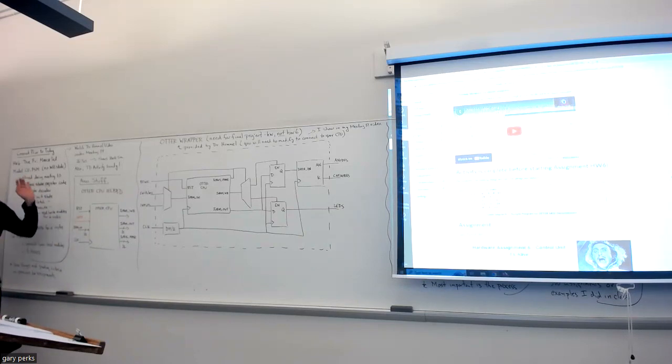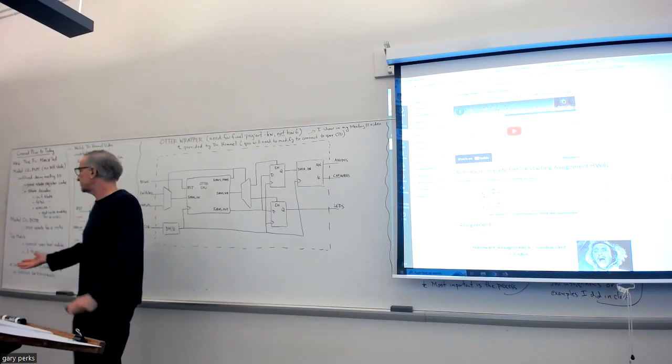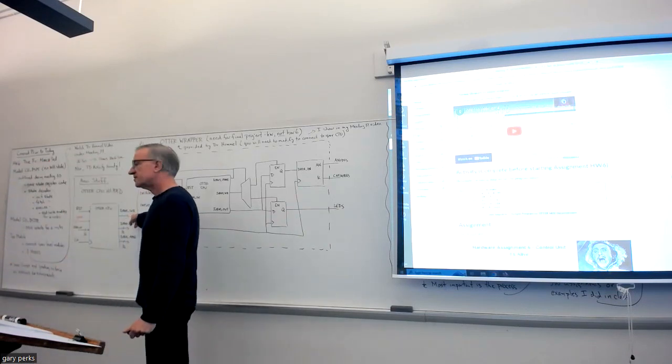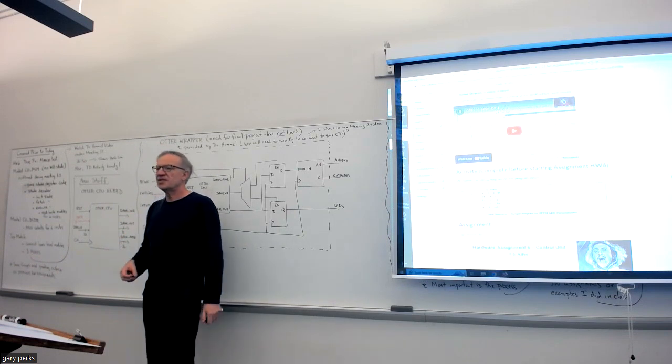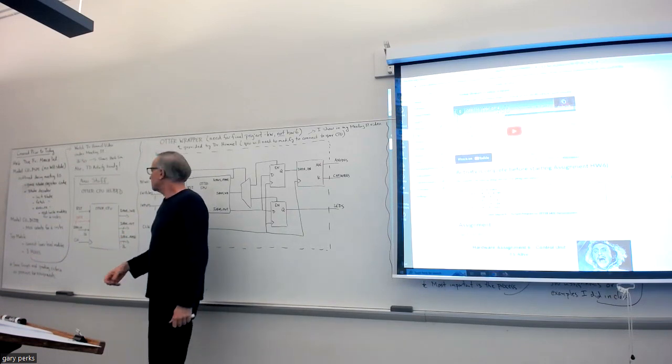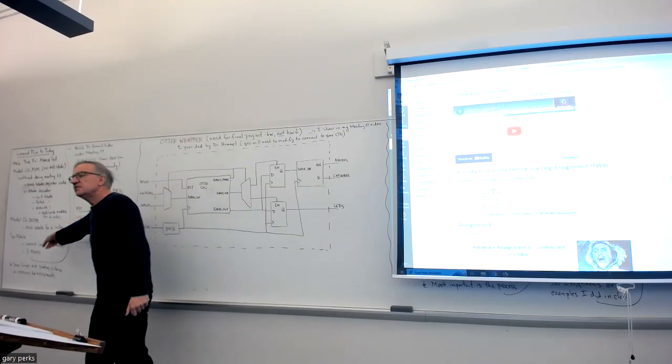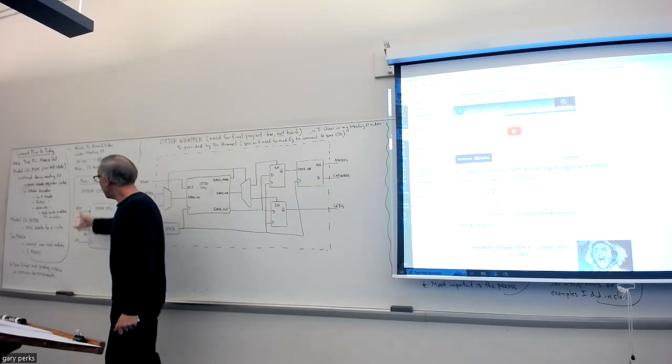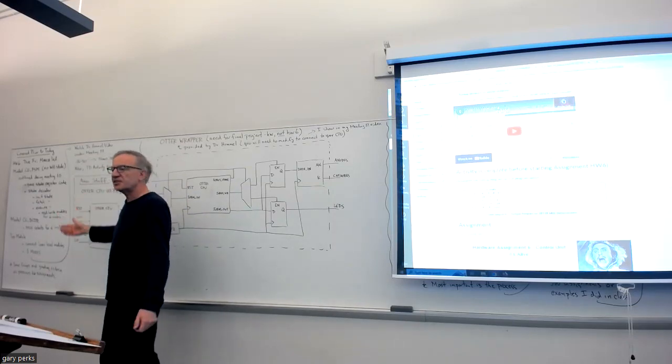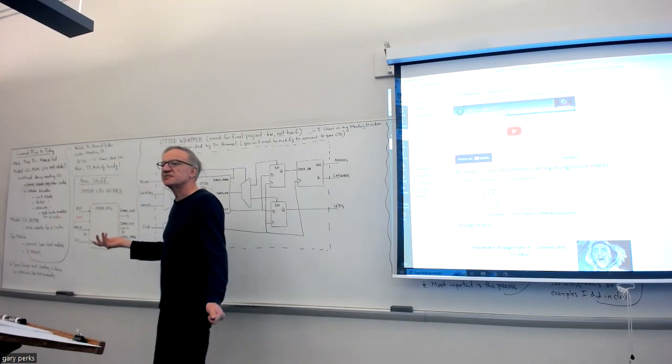So you can either omit it, not even declare that input, or if you declare it, just set it to 0. And then we only have 3 outputs: IO bus write, IO bus out, that's your data out, and IO bus address. So in your top module, you're just going to have to declare 3 inputs and 3 outputs.